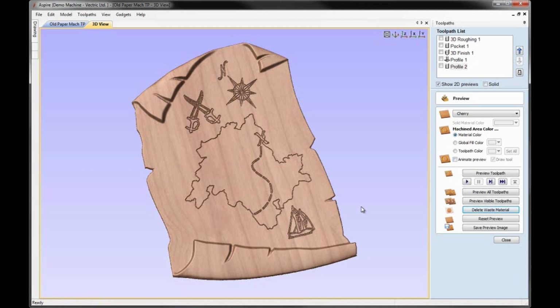And that concludes this particular example where we've showed you how to take the Parchment model we created in an earlier video and to machine it in a reasonably efficient way by creating boundaries to limit the area where we're 3D machining and create an area where we can 2D machine, in addition to being able to take the detail that we've got in here and profile that using a V-bit into the surface of the part.